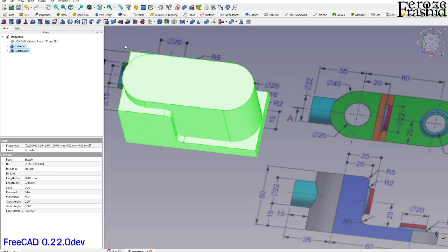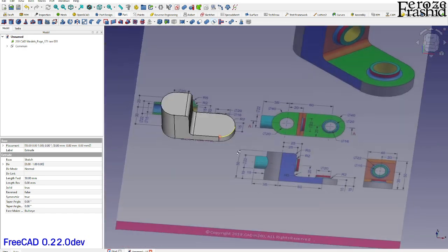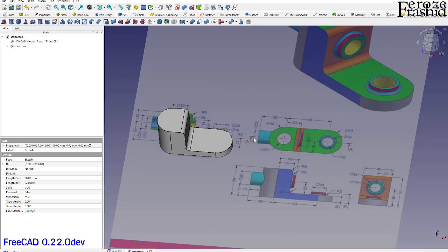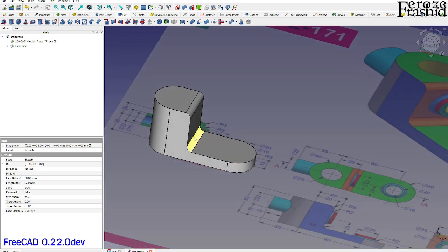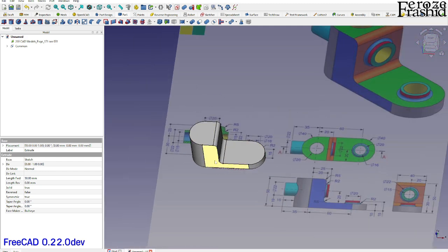Now I take these 2 and make an intersection from the Boolean operation, and that is our base object. So we get that. That was easy, in my opinion. Drawing one slot to build this pad and another half slot to build this, the approach that I took is much easier than drawing these two slots up there. So we got our base object.